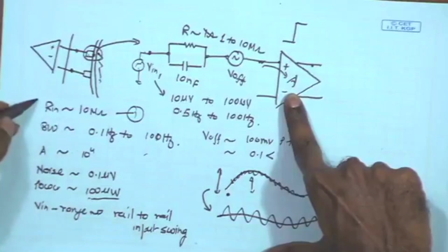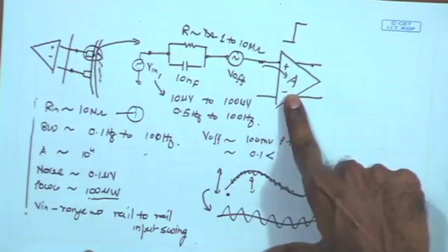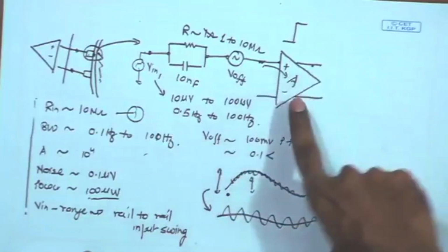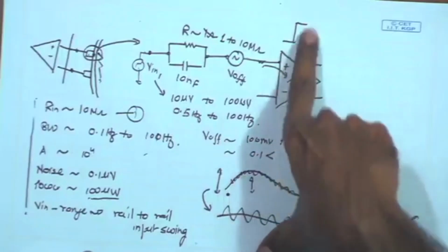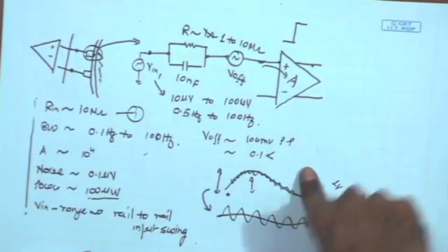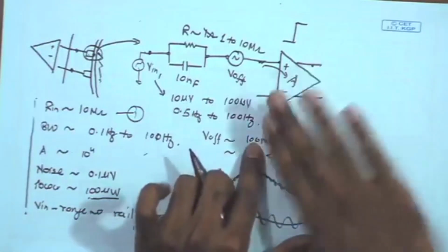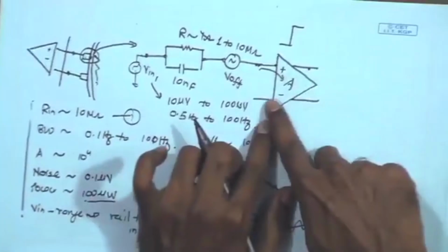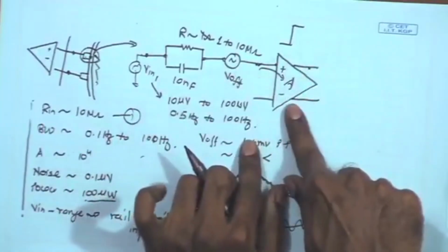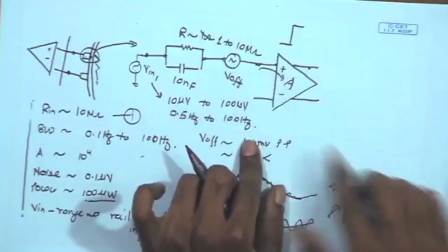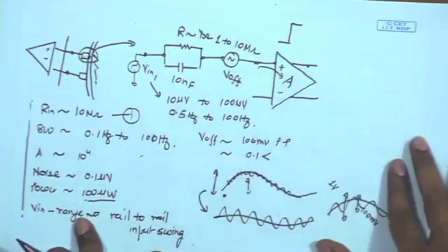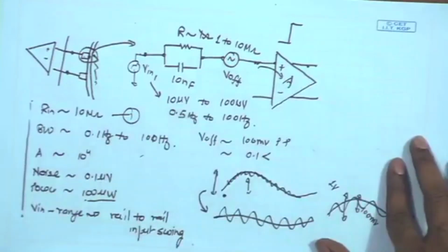So, here we have determined the high level specification for the very first stage, and we have assumed certain things. We have assumed that the first stage amplifier also has a high pass filter functionality built into that stage, and we are assuming that this is going to be broken down into multiple stages. So, this is not necessarily a single amplifier, it may have multiple constituents, but we are assuming the overall gain has been captured here, and we are modeling the overall gain as A, which is close to say 10 to the power of 4.